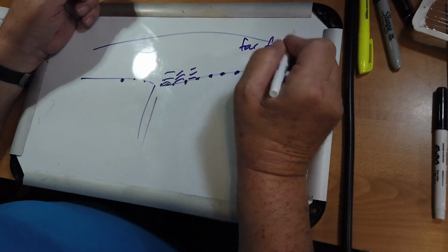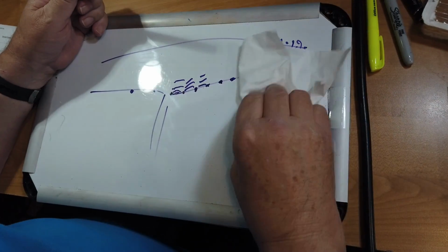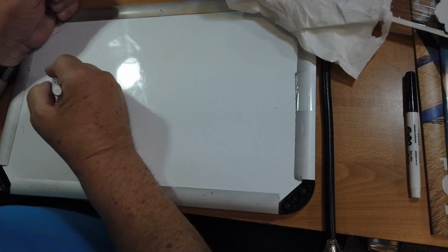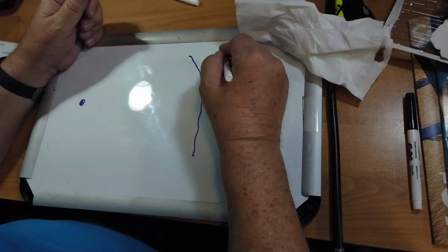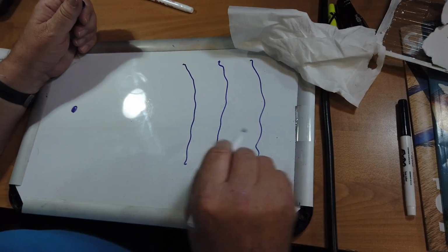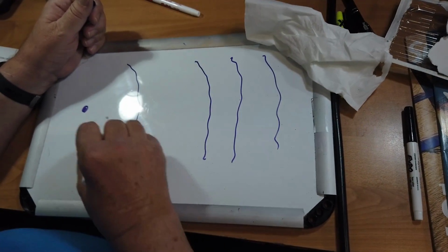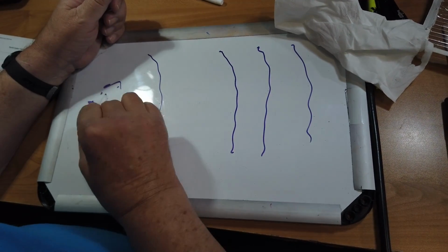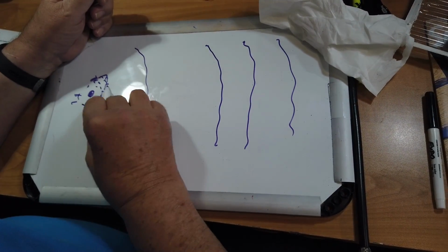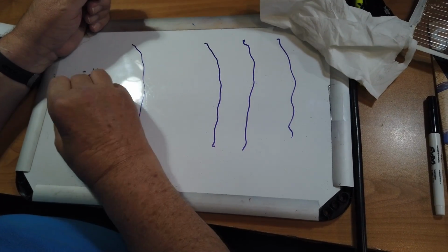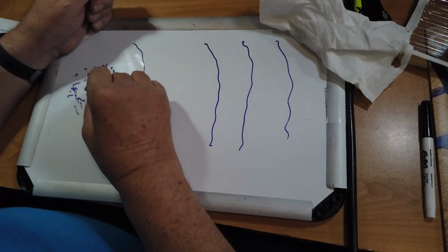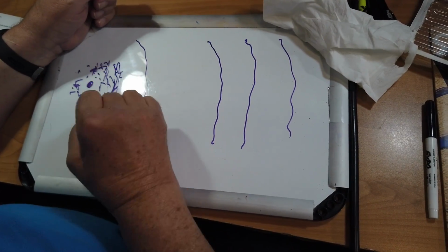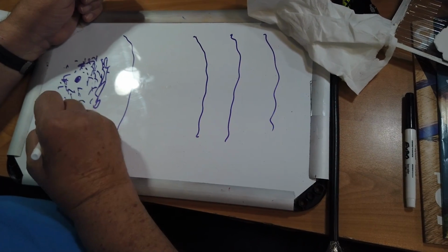Now, what is the difference between the far field and the near field? The far field is what we're used to. You've got an antenna here, and you've got wavefronts out here going away from it. Well, as you get in near this thing, you get all these little pieces forming their own wavefronts, and it looks like a mess. And then as you get further out, you start to see more of the wavefront type action. This is called the near field.